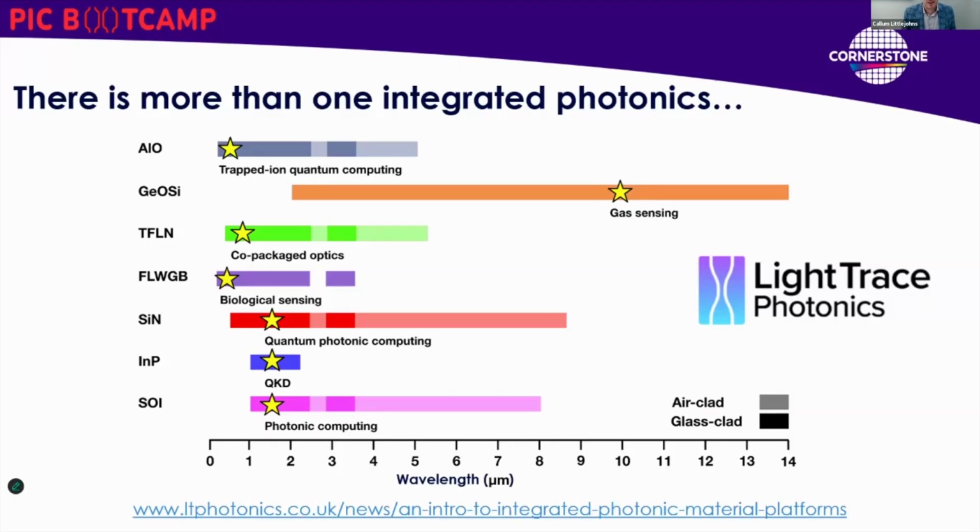Silicon as a material, at least with the most conventional modulation mechanisms, has a loss penalty that we can avoid, where when we create our modulator, we also introduce a fairly high insertion loss of the device, and introducing other materials like thin film lithium niobate can overcome this.